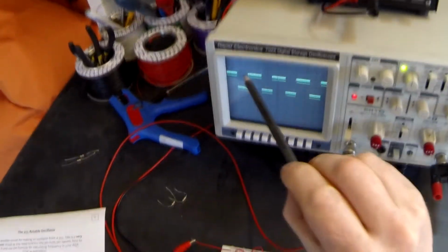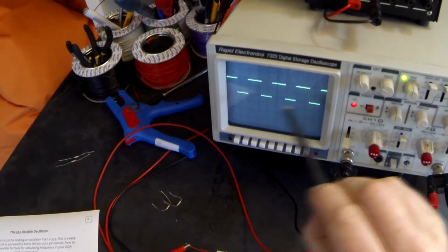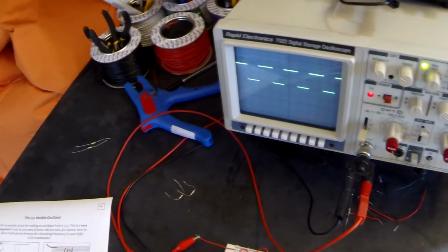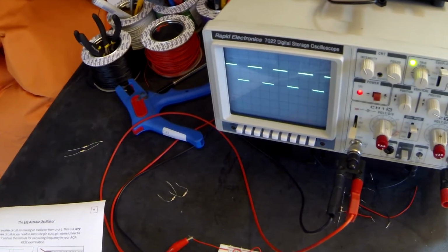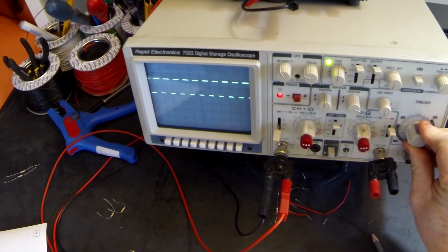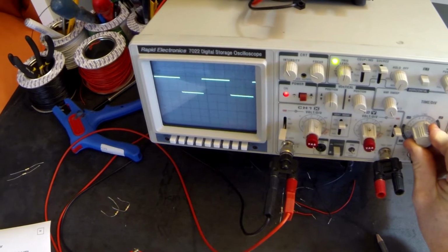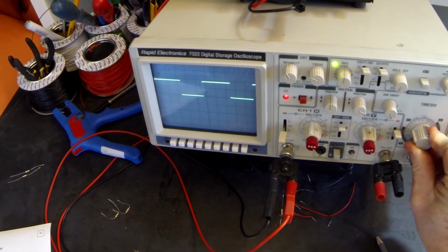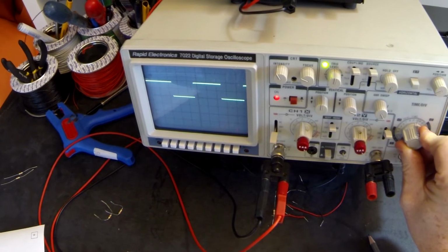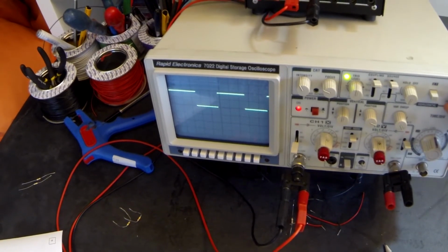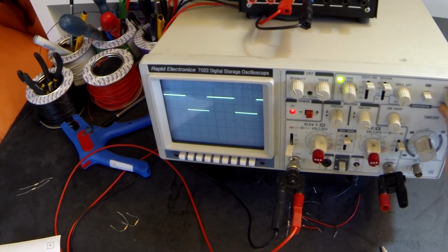There we go. So, looking at our oscilloscope, we can quite clearly see that the frequency has changed from what it was before, because I haven't changed any of the settings, yet I have far more waveforms on my oscilloscope screen than I did before. So, we're going to adjust our time-base settings till we get, there we go, that's probably the best setting. Going to position it so I can make my measurements easily.